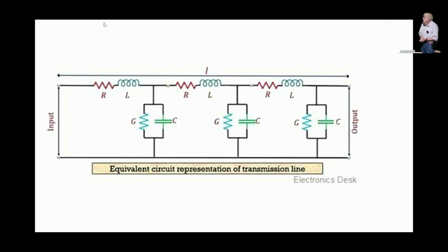But as you go up in frequency, the inductive reactance and the capacitive reactance become significantly more than the rest. So it really just comes down to series L and parallel C. And of course, that's a network that you can work with. So here we've got the idea that a transmission line is something that we use to get our transmitter information up to the antenna, but there's the potential to use it for other things because it is a network. And certainly the Smith chart is about that.